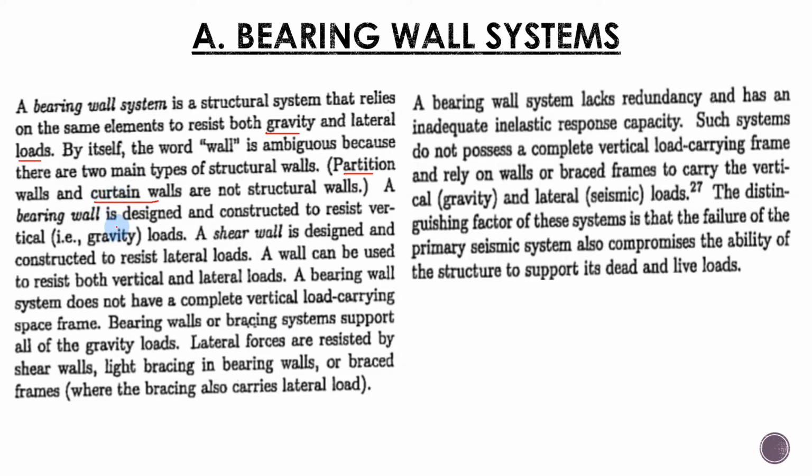A bearing wall is designed and constructed to resist vertical loads. Mao na ang makita sa mga buildings, mga bearing wall. A shear wall is designed and constructed to resist lateral loads. So a wall can be used to resist both vertical and lateral loads.